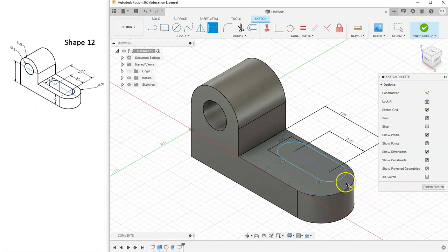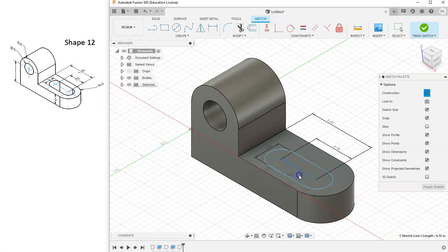And so you'll notice it's still not fully constrained. Let me right click and hit cancel. And I like to select shapes whenever they're not fully constrained and play with them and see why. And if you notice, it's because it's not centered in this shape from front to back. I cannot move it left to right anymore, but it can still go forward and back. Well, if we look, there are no more dimensions to give this shape. And so what are we missing?